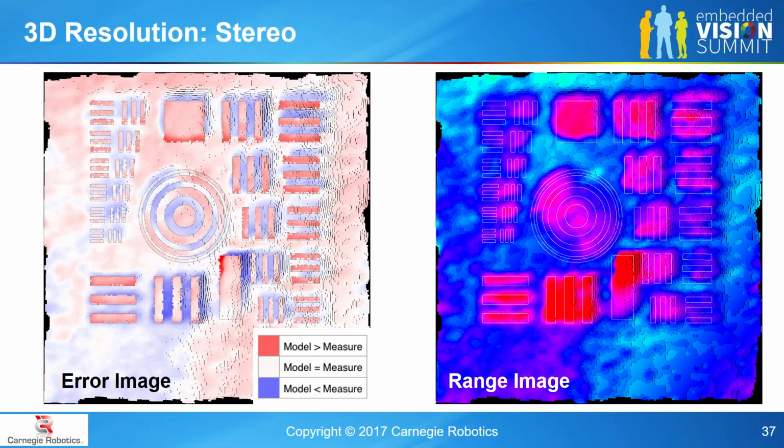And the way that the stereo matching algorithm also works is it's propagating uncertainty along that horizontal match. So it's actually blending a little bit more in the horizontal direction than the vertical direction, which is what causes this sort of webbing between the vertical bars and not the horizontal bars. You see on the right-hand side that the vertical bars are more observable than the horizontal bars. They disappear more quickly. And this is really interesting because with these large targets, you see the horizontal bars better. And then as the target gets smaller and smaller, that webbing actually helps you find the target. And you see on the left-hand side that even the very smallest target here is observable in the vertical direction, but not in the horizontal.